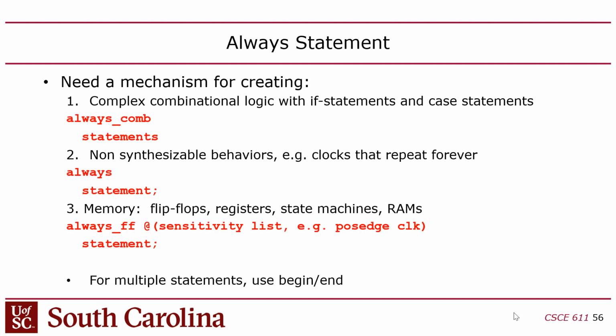Okay, so I mentioned two kinds of Verilog. There's structural Verilog, which is just instance this, connect this, right? Instance these things and wire them this way. That's basically just creating a schematic. Then you've got behavioral, which is logic behavior. It's like the Boolean logic stuff, right? And all I showed you for that was the assign statement, the continuous assign statement. It just assigns a value.